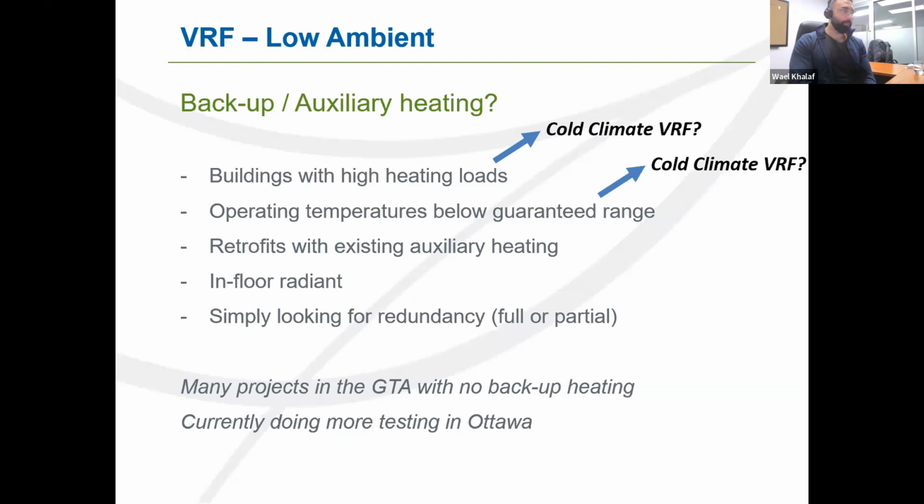But in Ottawa, for example, we do dip below -20 and definitely below 0 Fahrenheit, which creates a lot of hours where we might not necessarily have our nominal heating load, and we might have some units that will trip on low suction temperature.